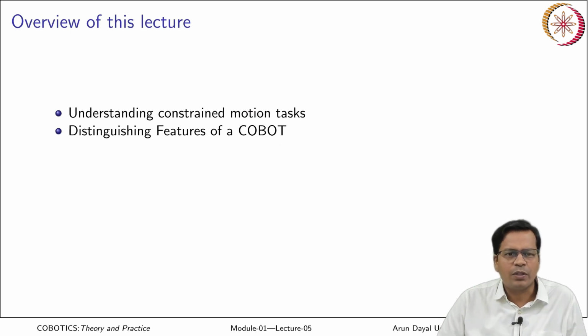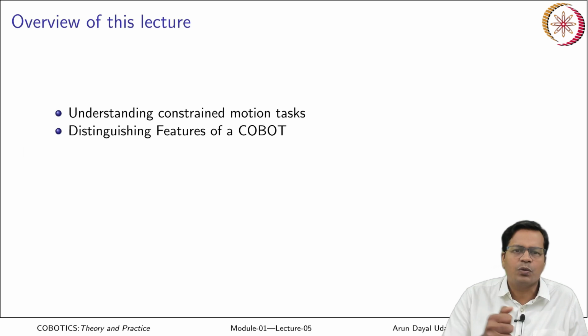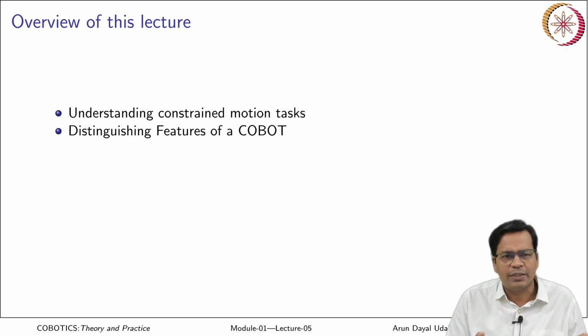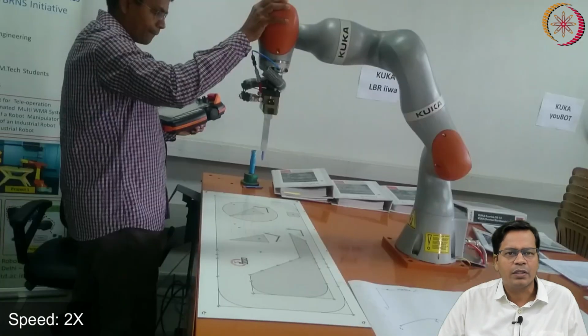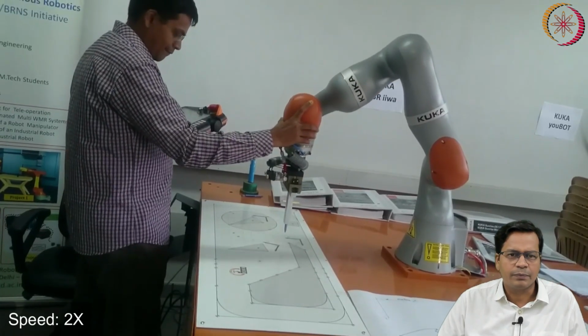Let us first have a look at the lead-through programming that we have heard of quite often that a cobot possesses. You can take it to any point and teach it, instead of jogging it to a location and teaching it. So, this is something very innovative that has come with the cobot. Let us have a look at that.